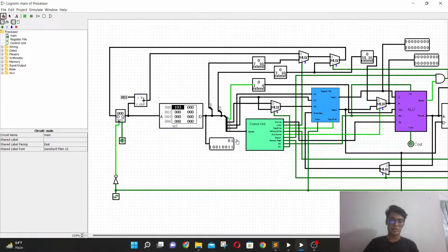Then two 2-bit registers go inside the register file, and the value of S2, which is our RS here, is being read inside the ALU in the input pin B, and in the DST input pin, our constant 1 is being inputted, and then the result of the ALU is, like before, being written inside the register file in the write data.